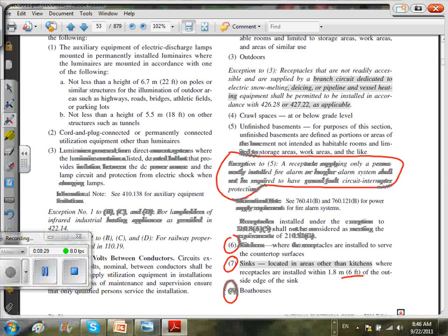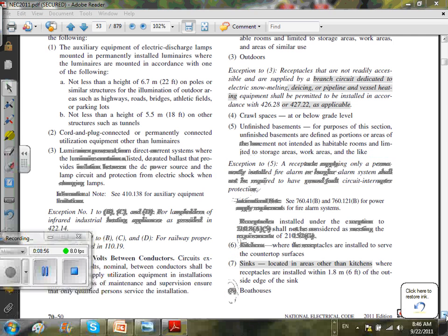Meaning, if you knowingly know that the only place, for example, you have just a tiny little slot for your freezer, and you put a receptacle right there, knowing that there will be a freezer thrown right in front of it, you might have to put your receptacle a little bit higher than the freezer. If you don't know, you can't control, as we said, people's behavior. Any question, guys, about the location? And they have to be readily accessible.